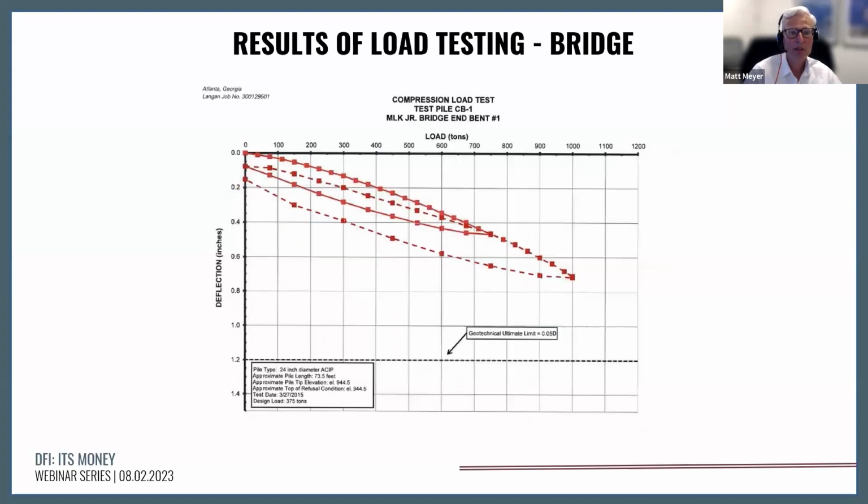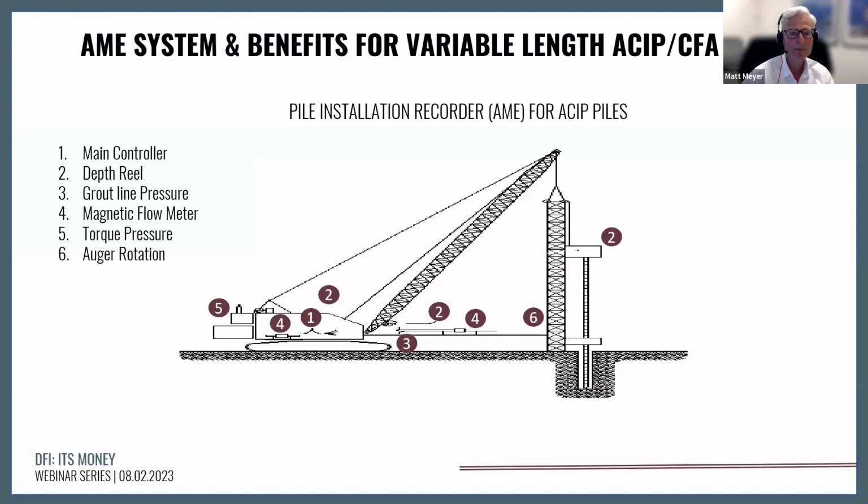Now moving on into the end bearing pile within the bridge, a little more rigid response. Again, GEC 8's geotechnical ultimate limit state shown there as a failure criteria. We're well above that, satisfactory performance from a load carrying perspective.